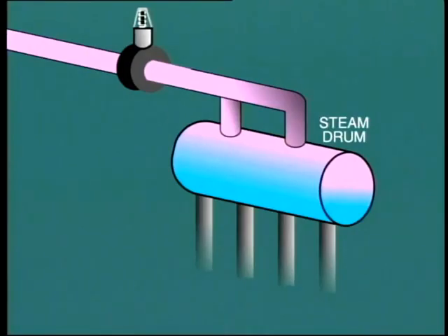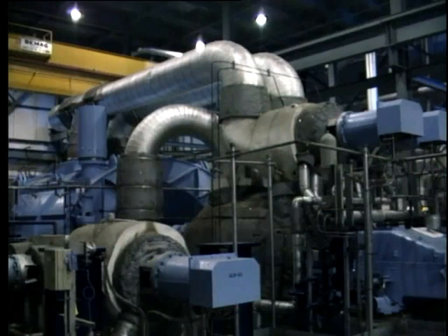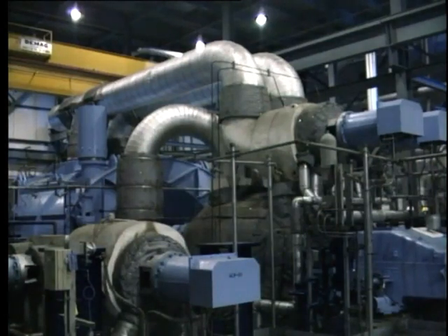In many industrial processes, saturated steam is quite adequate for the job at hand. In these cases, steam can be provided directly from the boiler steam drum. However, in many situations, it may be essential that dry steam is supplied. If the steam is used to drive a turbine, we would also like the temperature to be higher in order to improve the efficiency of the turbine cycle.